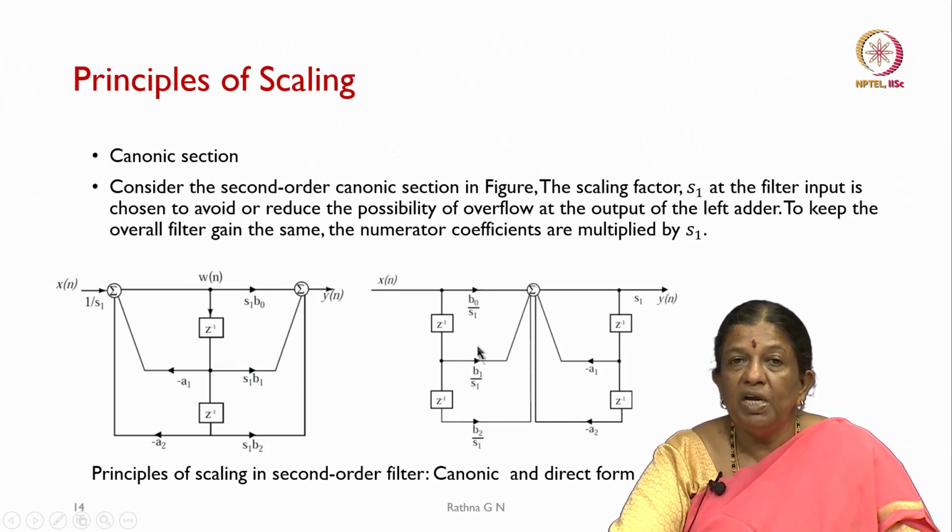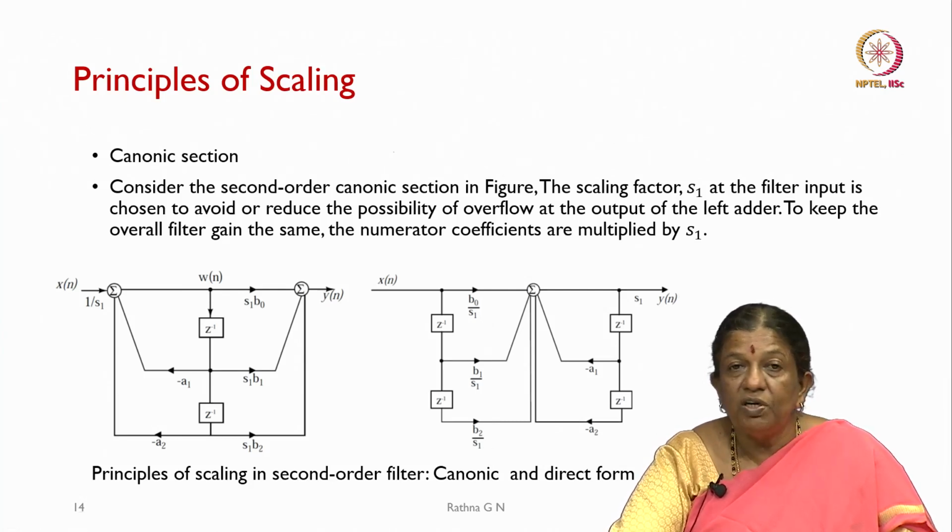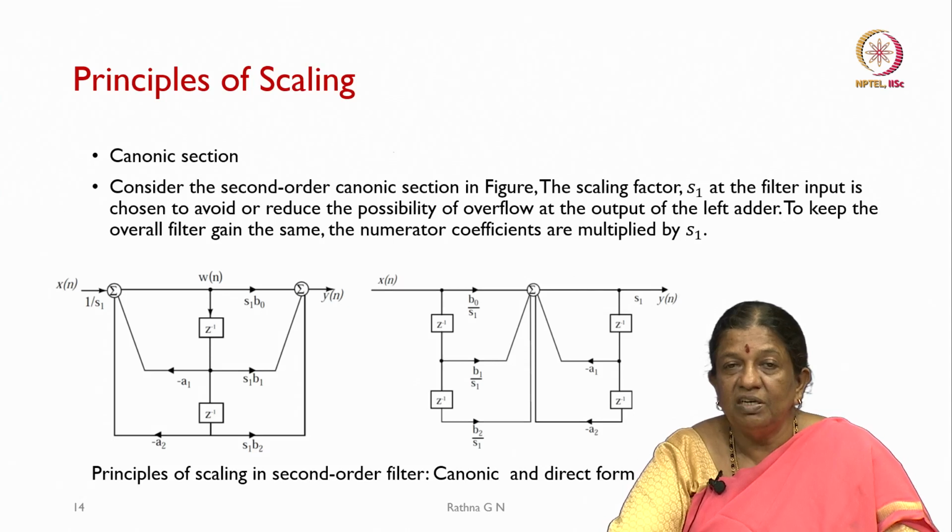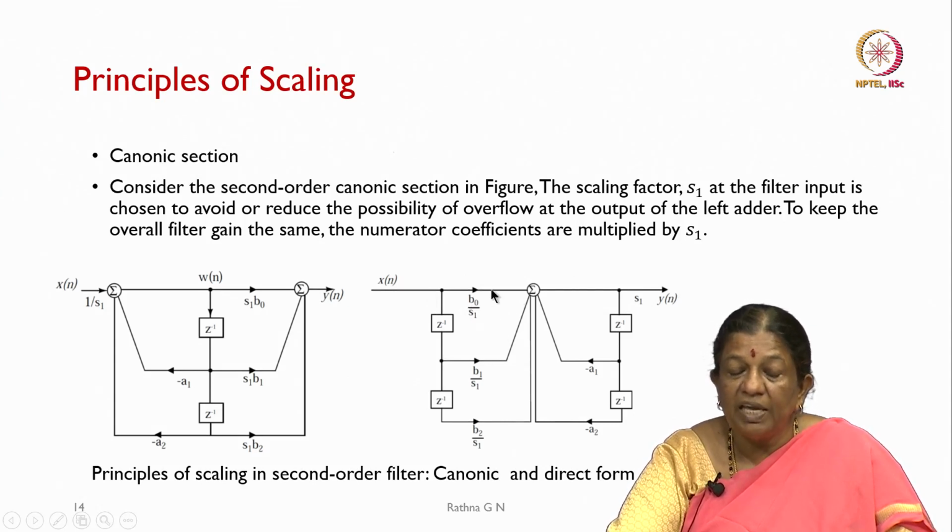When we are loading our coefficients itself, we can scale them if they are powers of 2. If they are not, then you will have a little computational involvement in designing your IIR filter. In the end, what you can do is scale the output by the S1 value.